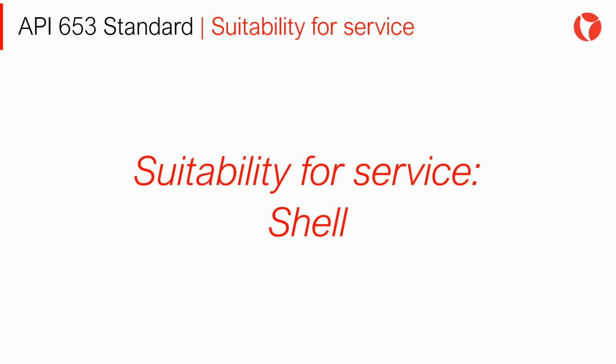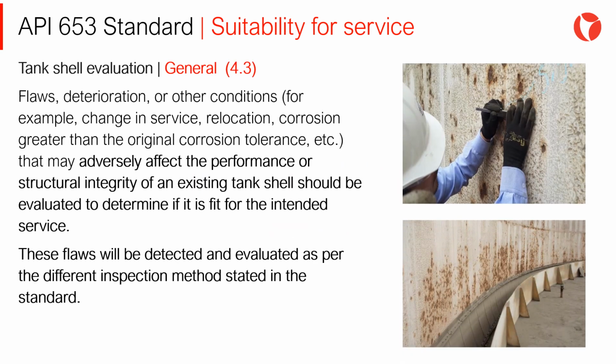Now let's talk about the suitability for service of the shell. Tank shell evaluation. Flaws, deterioration, or other conditions, for example change in service, relocation, corrosion greater than the original corrosion allowance, etc., that may adversely affect the performance or structural integrity of an existing tank should be evaluated to determine if it is fit for the intended service. These flaws will be detected and evaluated as per the different inspection methods stated in the standard.